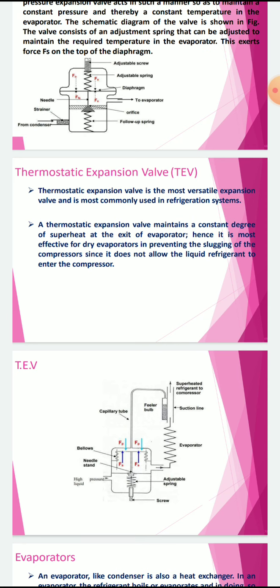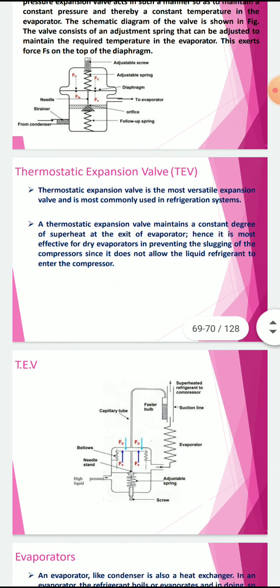Hence, it is most effective for dry evaporators in preventing the slugging in the compressors, since it does not allow the liquid refrigerant to enter the compressor.